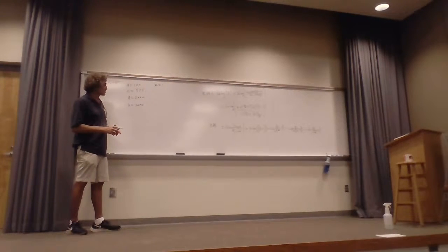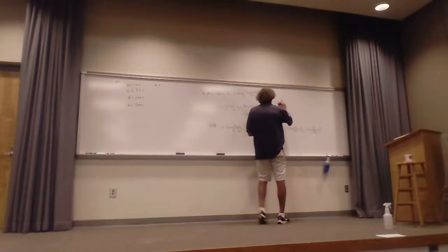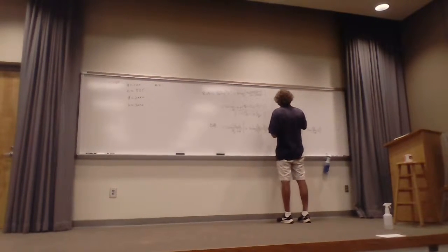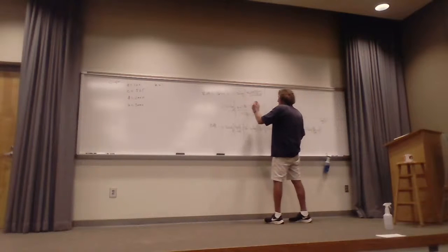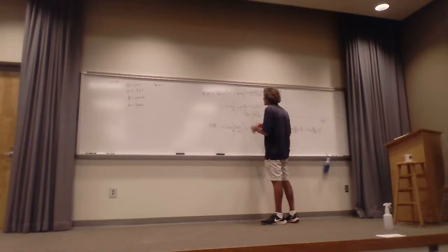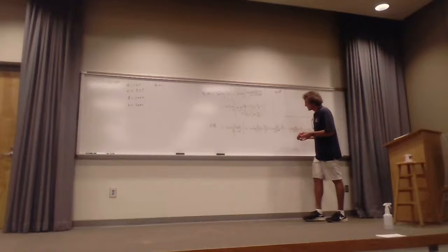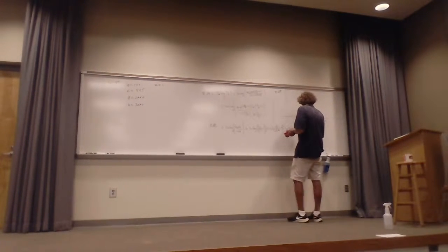Well, what I want to do is plot, let me do it at this corner of the board, versus log of omega, the value of this. So it's in dB, I got the 20 ahead of it. So if I look down here, I know for a very low, first the lowest frequency is A, so I put A down here.